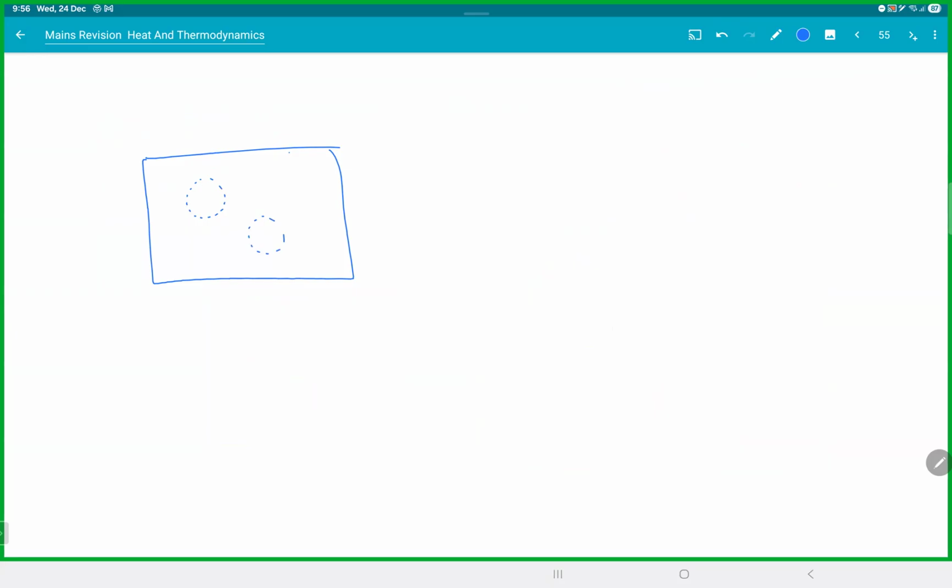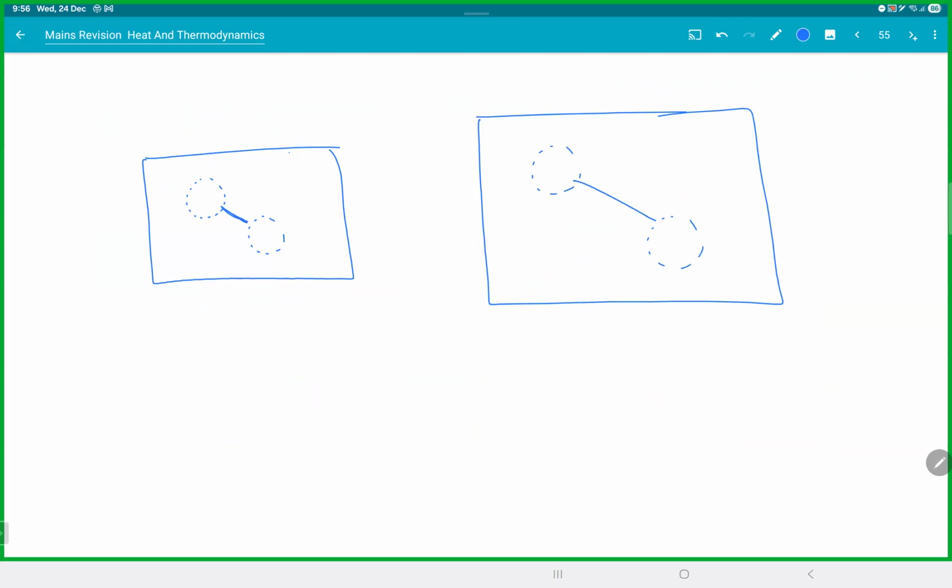Now increase the temperature. What do you think will happen? The whole thing will expand. So even the dotted lines will expand. Now remove the cavity. Do you still think the distance between them will decrease? You're getting it? So even if you have a cavity, cavities will expand, agreed, but the material between them also will expand. The cavities will get pushed away. Are you clear with this thing?